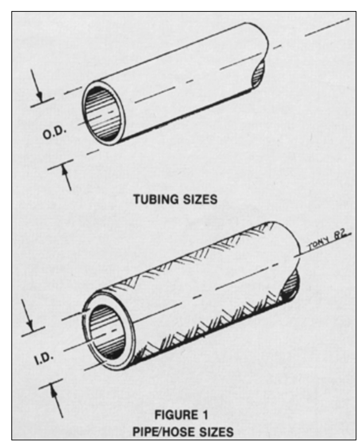What is the purpose of using quick disconnect couplings in fluid lines? Disconnecting a line without a loss of fluid or air entering the system. How is metal tubing sized? Outside diameter. How is flexible hose sized? Inside diameter.